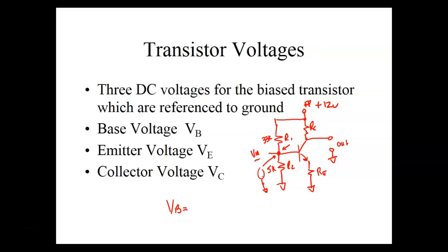So what would be the voltage? And guys, you are calculating an amplifier. And I'll show you, it's really, really neat. So what would be the voltage drop across the 5K? Where did y'all learn to do this at? DC. That's all we're trying to do, calculate the voltage drop across that, and that would be VB. See how we got that? Pretty simple.